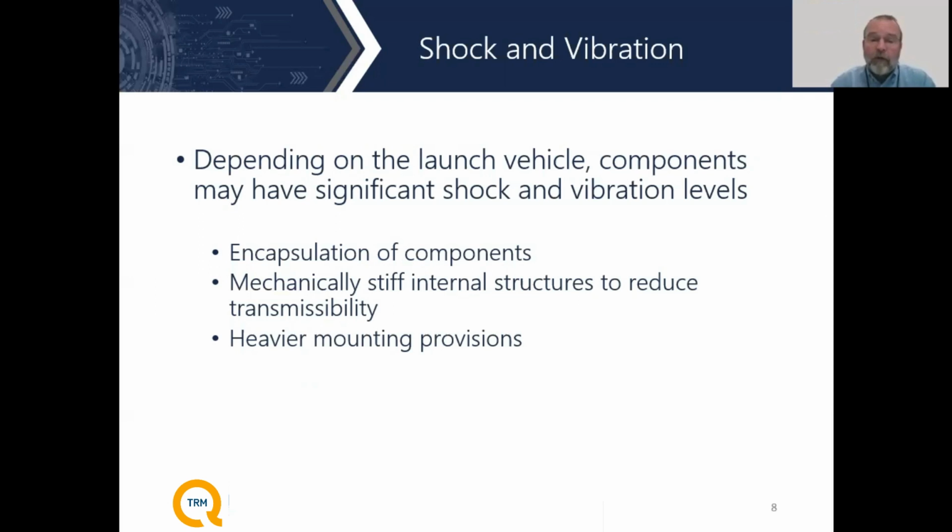Also, we make sure that the mounting provisions are heavy enough that we're not mechanically stressing any of the mounts. So a lot of work is involved here, very critical. It's not just a matter of making sure that the parts look good and work well electrically. They have to survive the trip to space, which is very often quite a critical part of the entire operation.